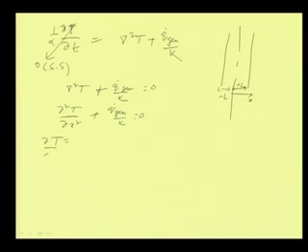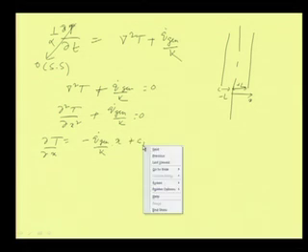Now, if we solve this equation, what we find is dT by dx equals minus q dot gen by k into x plus C1.